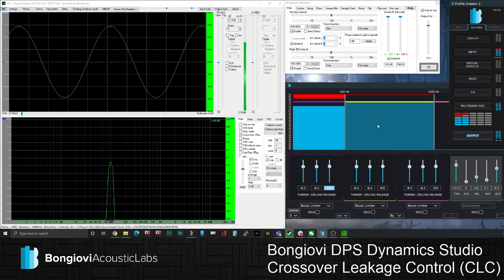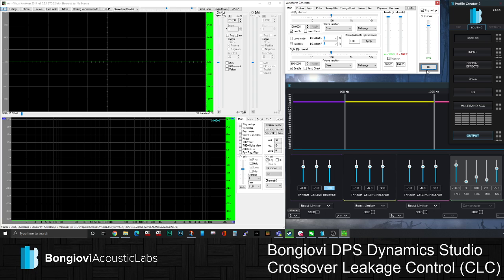Now this is very useful in the case where you've got a small speaker and you want the low frequencies to be controlled all the way up through that crossover so you don't have distortion happening in your system. So if you set it to favor the right side band or your middle band, then all of the content up through the crossover will be handled by the low frequency AGC. That's super important for preventing distortion and all that from low frequency signals.